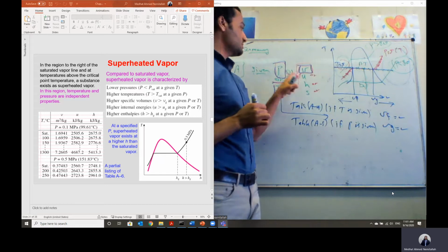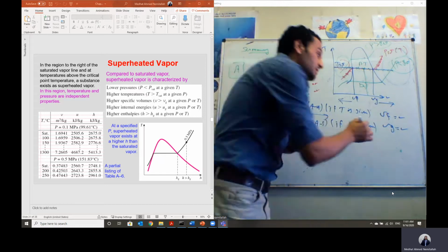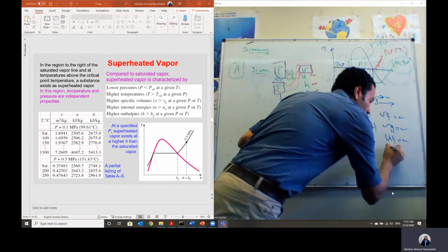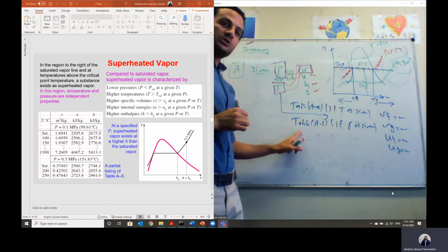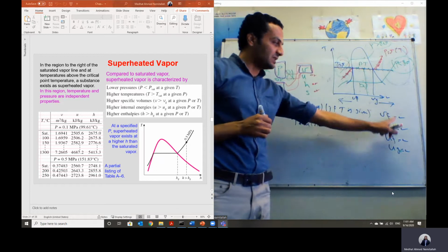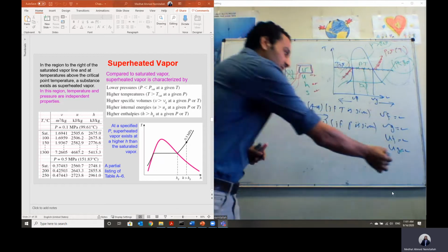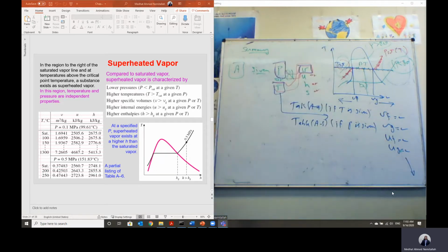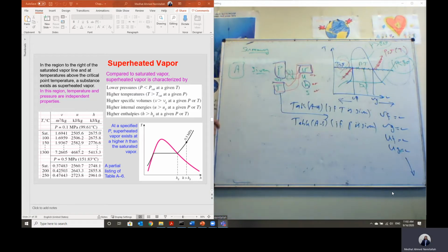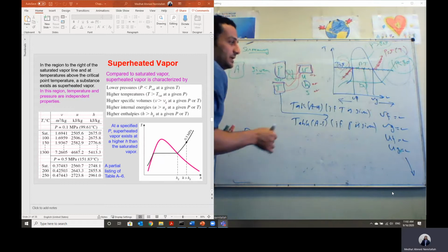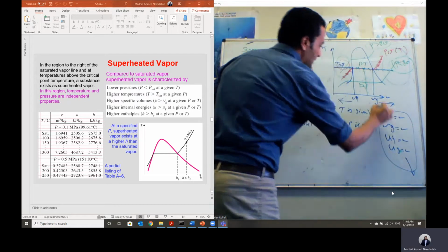But let's say pressure is given with the internal energy. Then in this case, I will get U fluid, and also the value of U gas at this given pressure. If the temperature is given, go to table A4 and get the same properties. Similarly, we can get the other properties. Let's say if H is given, then I will get H fluid and H gas. And we have two options in this case. So first of all, I will compare those values to the given value.